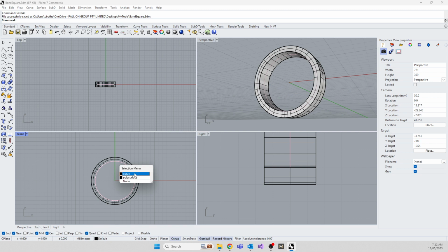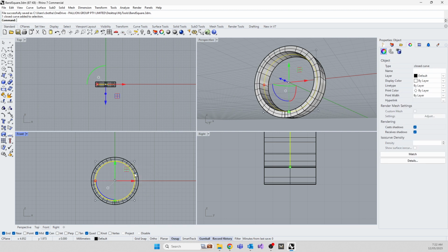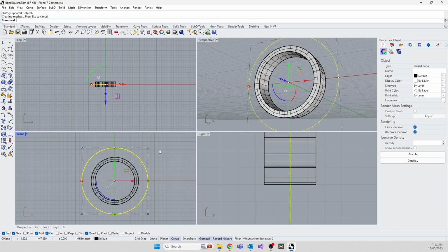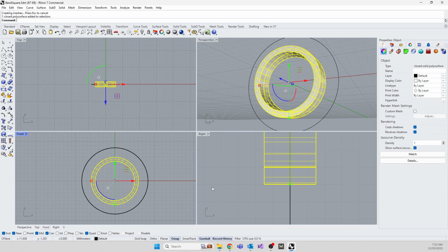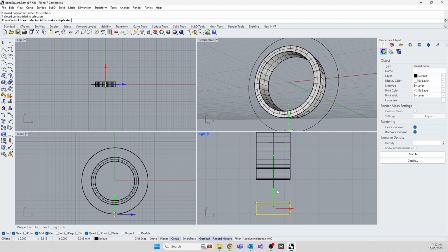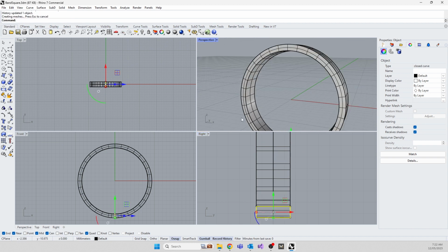I've got a ring that was 10, so I've got to make a ring that's 16.8. I go scale from 0, and we know that it's 10. I can scale it by 0.1 to get back to 1, and then scale it back up again. Scale from 0, and then my scale factor is 16.8. Maybe it's faster to draw the circle, I don't know. I'm just saying that you now have the ability to bring out constructs as quickly as you can. If we don't break the history on this, you can quickly make a ring.